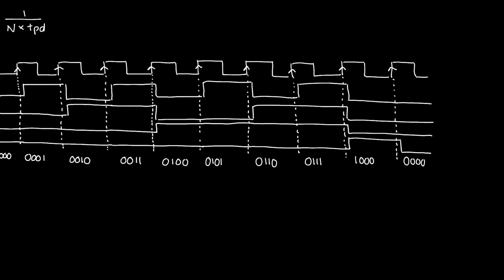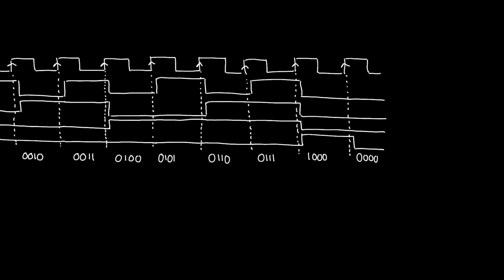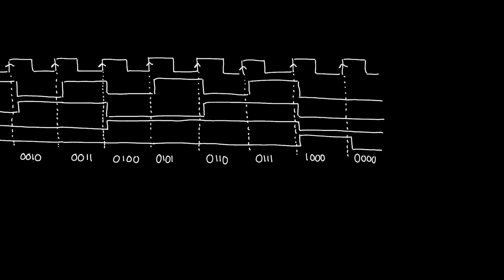The other thing is that what I would see in a Mod 9 counter is, if you recall, that weird glitch where over here, Q0 would toggle as usual, and then it would sort of momentarily be high enough to activate that NAND gate, and then it would go back to 0. So I would have this little voltage spike over here.